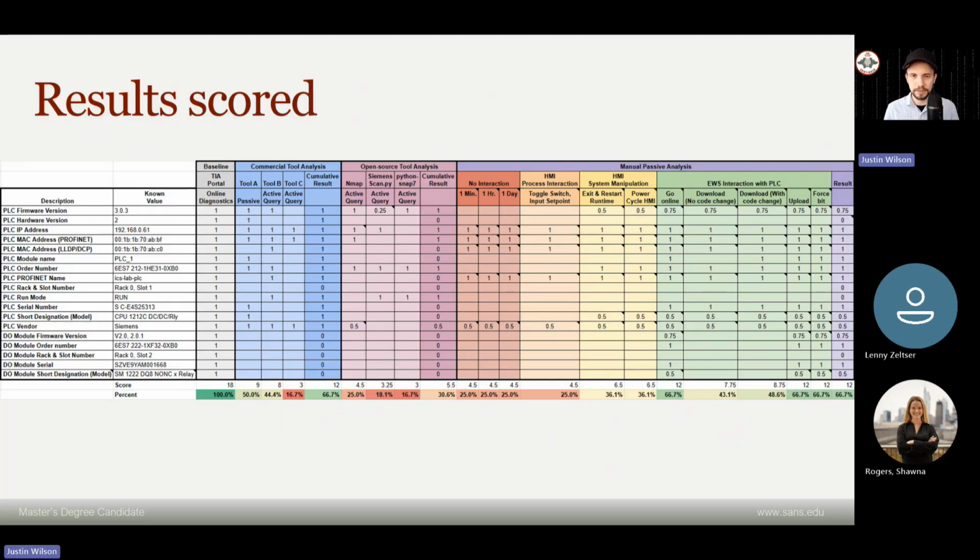And this is significant because it means that a low-risk activity like connecting to a PLC can produce a lot of asset information. You don't have to do a download or an upload or make some kind of potentially disruptive change. All you'd have to do is connect and disconnect, and you can get quite a bit of information that way.